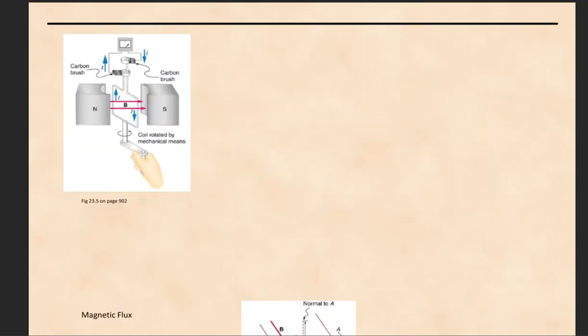Now, it's not really feasible to generate electricity by waving a bar magnet back and forth near a coil of wire. Usually our mechanical system is best suited for causing something to rotate. And so if we have our mechanical system make something rotate and we attach that to a coil of wire inside a magnetic field, then we see, connecting this wire to a galvanometer, that while this is rotating, current flows, as evidenced by the galvanometer needle swinging back and forth.